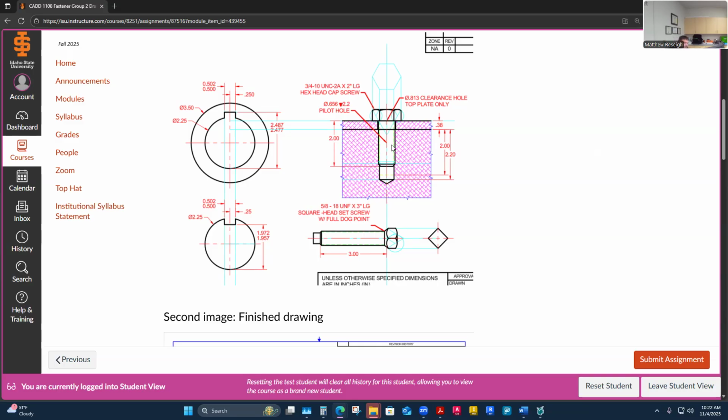What you can't have when you do that is an upper plate with a hole that's too big or too small for that fastener to pass through. There are no threads in this one for it to go through. It's going to be held in place by the threads in the lower plate, the relationship between the external and internal threads holding it together. And then the head of the bolt itself is what holds this thing so it can't fall off, right? So what we have going on there is a clearance hole through that upper plate. We'll draw that relationship this week, and that's a real specific thing too.